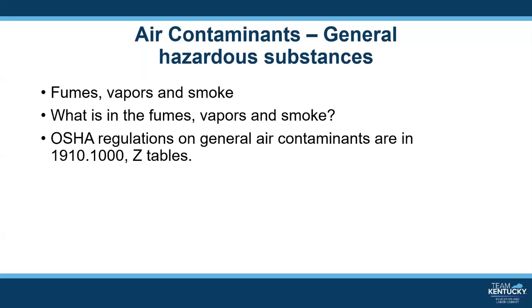Many of these fumes that are created from general welding processes are regulated by OSHA under 29 CFR 1910.1000 in the Z tables. These welding fumes can cause serious health problems for workers if inhaled. Short-term exposure can result in nausea, dizziness, or eye, nose, and throat irritation. Prolonged exposure to these fumes can lead to nervous system damage or kidney damage.